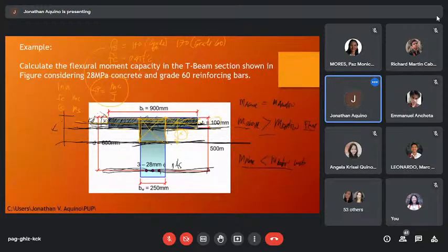So from that, the analysis is the same, whether singly reinforced, doubly reinforced, irregular shape or T-beam. For a rectangular beam, we have direct formulas. But for this one, you just transform it into an equivalent area of property. So the transformed section is applicable for all types of beam, whether doubly, singly, or irregular section.